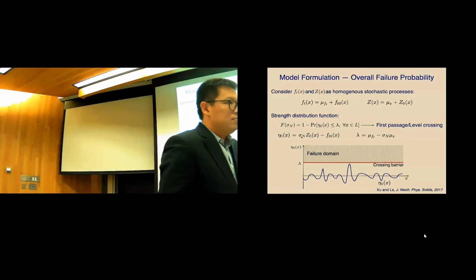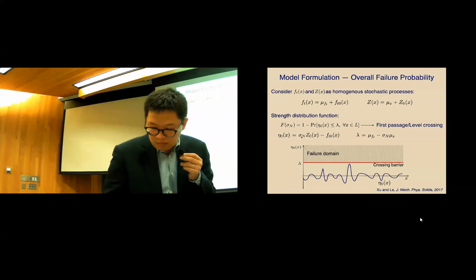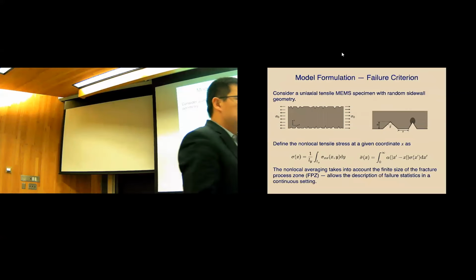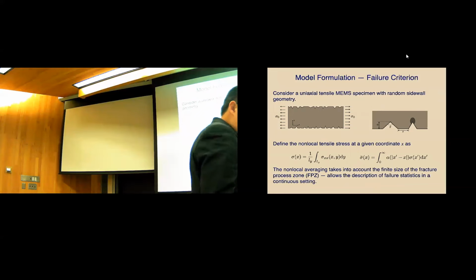Okay, yeah, I have a question similar to Emmanuel's. Could you go back to where you compute the average stresses for your strip? Those singularities, I understand you don't take them into account directly, but they will affect the variation of that sigma bar x, right? How do you take them into account, and how do you take into account that not only the sigma x will vary, but the shear stresses will be affected as well because of that variation, by equilibrium? So what do you do with the shear stresses? Do you consider them?